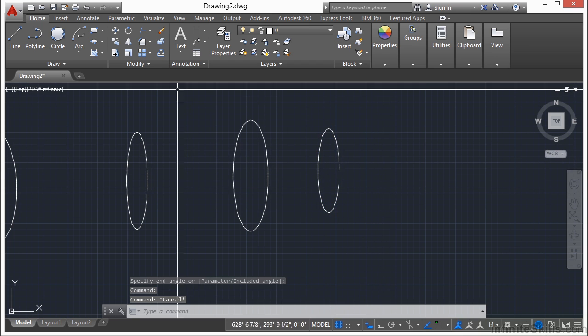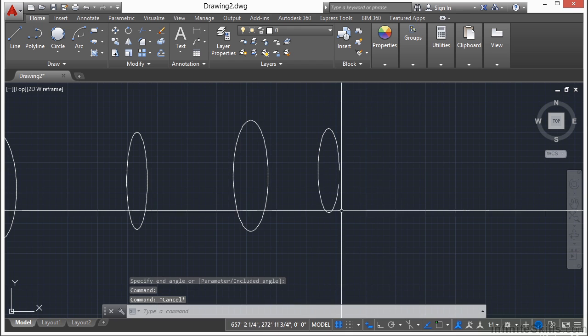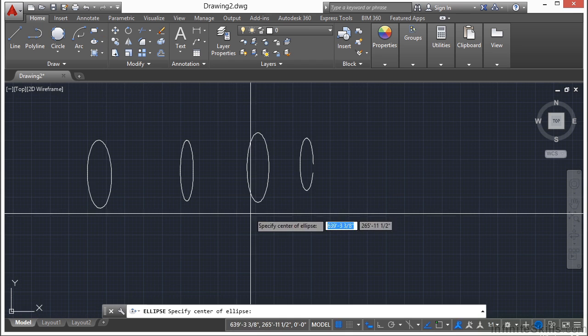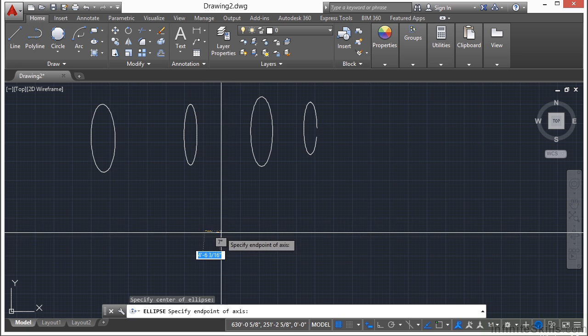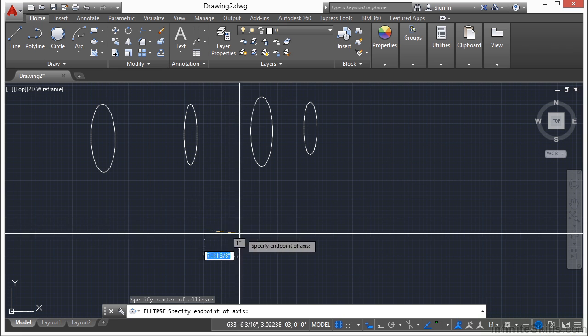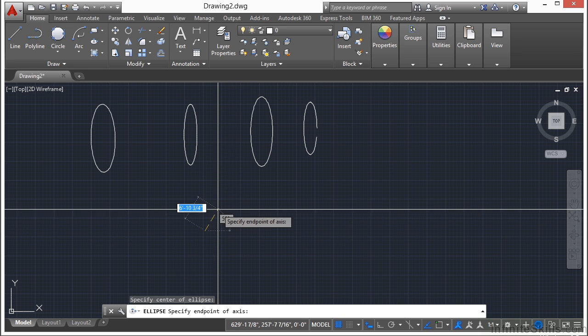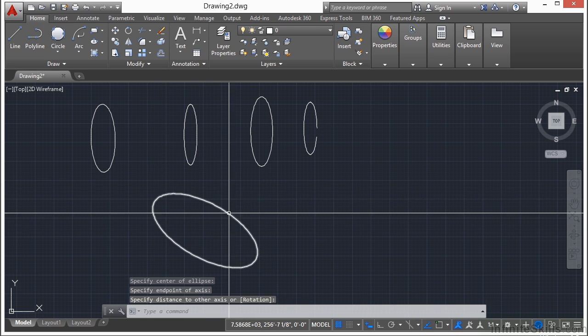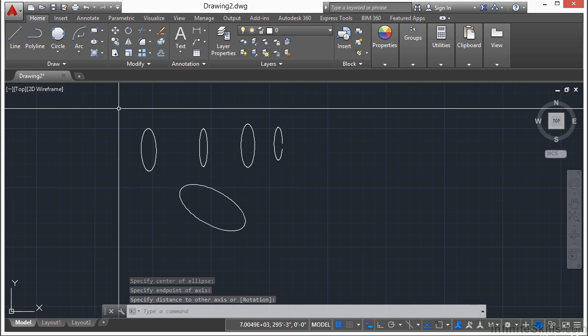Now the ellipse, keep in mind, if your ortho command is turned off, like I have mine off right now, when I pick my center point, and then I pick my width, it's going to be drawn at this angle. It's not perfectly horizontal or vertical. So it can be oblong like that. So there are a lot of different ways to draw it. And it depends, again, on exactly what you're trying to draw, the perspective of it, or what information you have at the time.